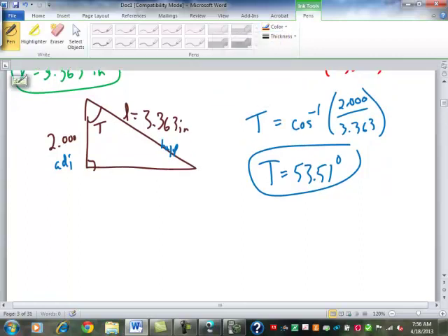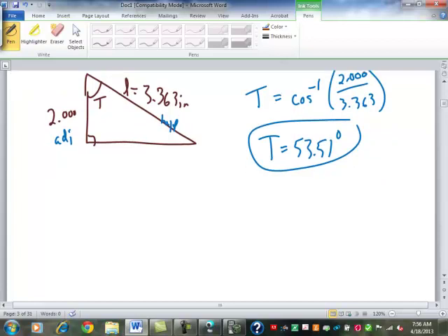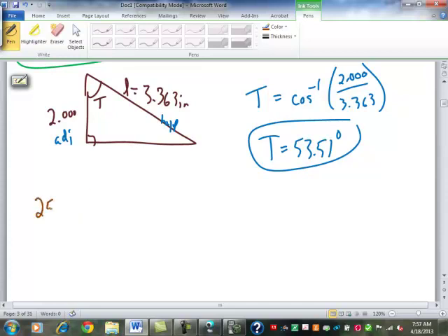So let's take this the next step. If we have a carbide drill bit going into steel, what's the common surface cutting speed? What's that? Carbide. What is it, about 250? So 250 feet per minute, right? If we are making a 1/2 inch hole, how many RPM can we turn this?